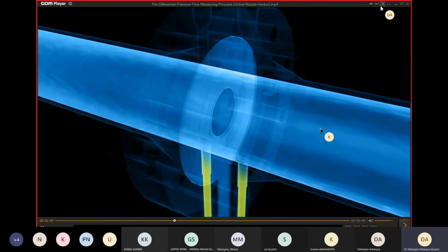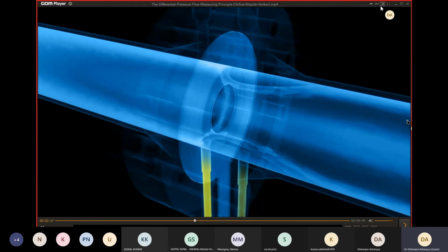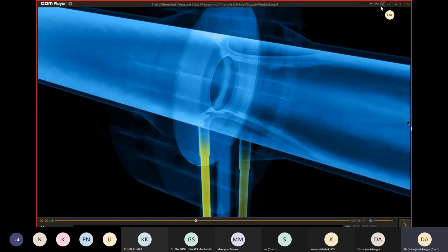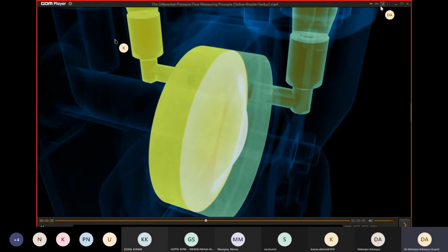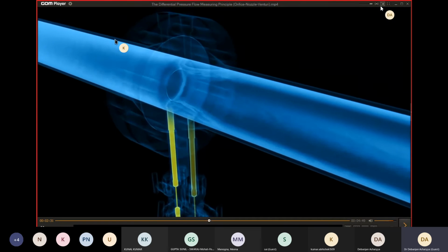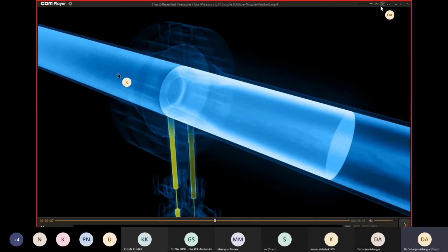If the fluid is not flowing, the pressure before and after the orifice plate is essentially identical. As soon as the fluid starts to flow, its velocity around the orifice plate increases significantly because of the restriction in the cross-section. At the same time, due to the laws of fluid mechanics, the static pressure at this point decreases. Consequently, different values are detected in the pressure chambers of the sensor, a higher pressure before and a lower pressure after the orifice plate. This pressure difference is a direct measure for the flow velocity, and thus the mass and volume flow in the pipe.